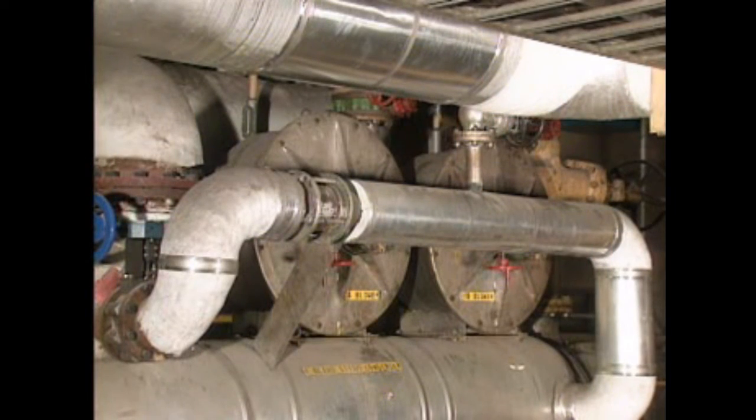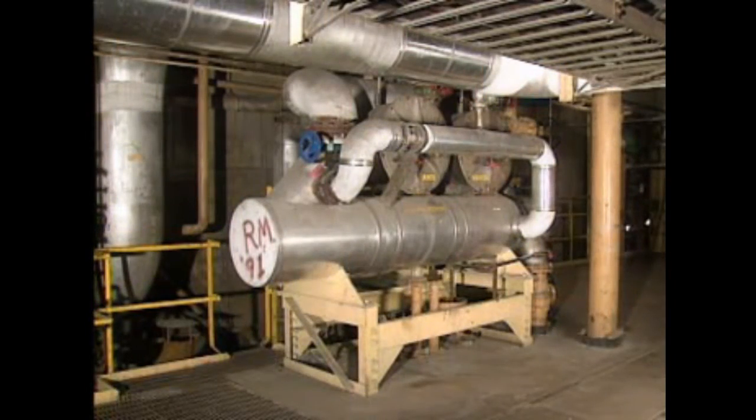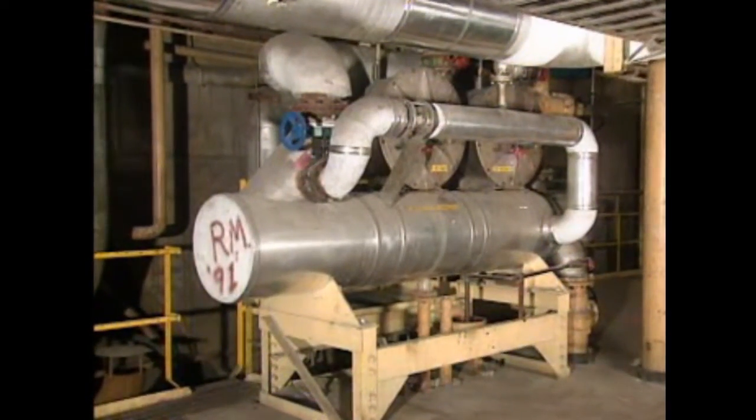You should also make certain that the exhausters are working properly and that there's a vacuum in the condenser. And finally, check to make sure that the condensate water level in the Gland steam condenser is being maintained at the proper point. There's usually an indicator that allows you to determine the condensate level. We've seen how the Gland steam seal system and Gland steam seal exhaust system work. We've also reviewed some common checks that are made on these systems.